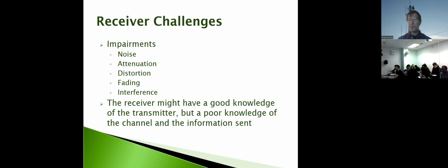In a simple case, if you assume that between the antennas there's a direct path, and then there's also a reflected path, let's say it's reflecting off some big building or a mountain or some walls inside, then that reflected path is going to take longer to get to the destination, meaning it's going through more phase shifts.